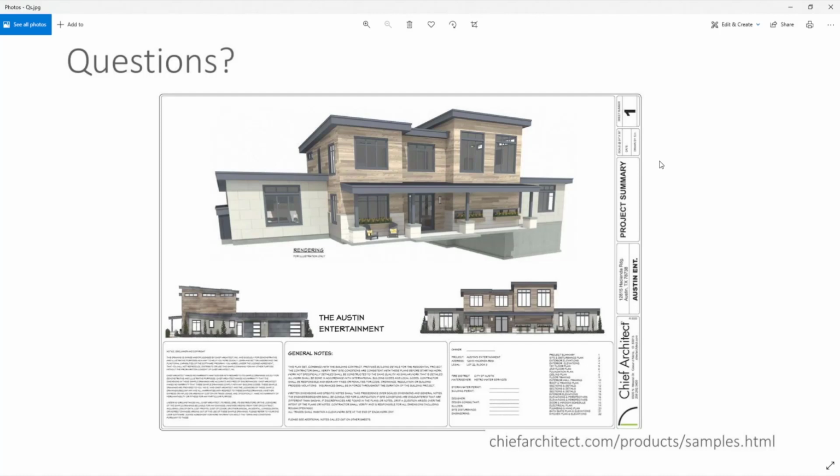I typically don't, because when the program builds the roof, or you move the roof, or you manually edit the roof, the program is designed to have the walls join and meet up underneath the roof. So when you have the automatic roof builder on, and when I built this model, I was changing walls from hip to gable to shed.